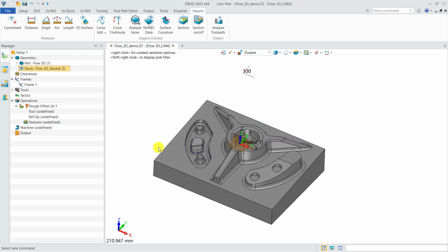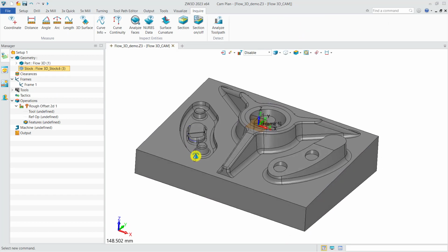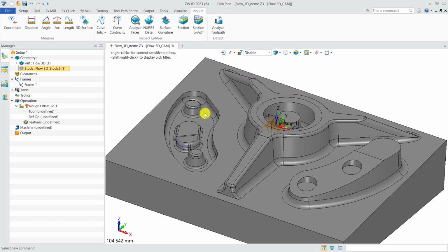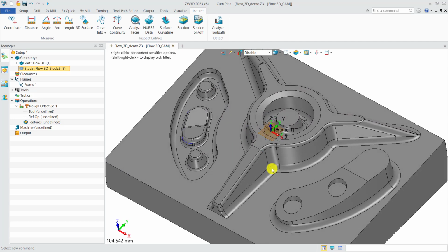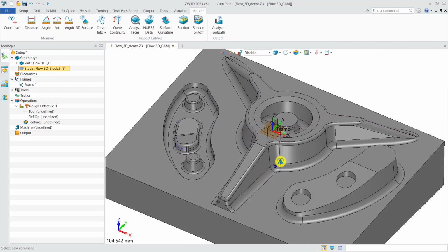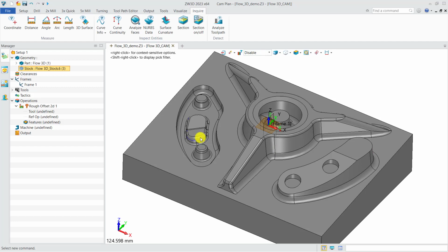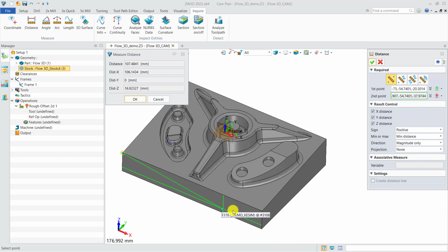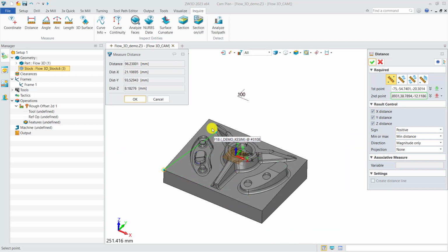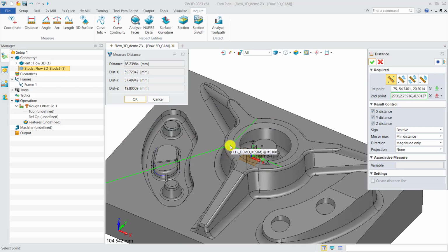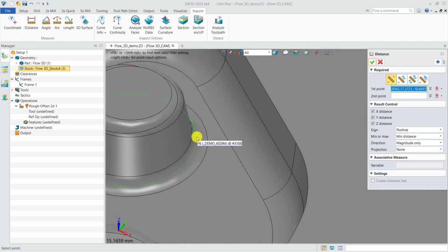The next step, we need to analyze the workpiece, like the overall size, depth of the features, corner radius, especially the narrow areas. We can get the overall sizes in the steps when creating stock just now. We also can use the inquire commands, length, width, and depth. And the rough distance in some narrow areas.